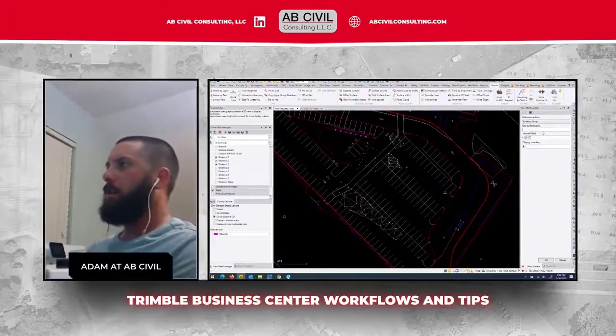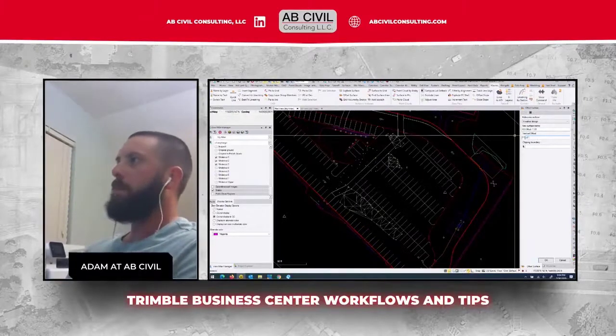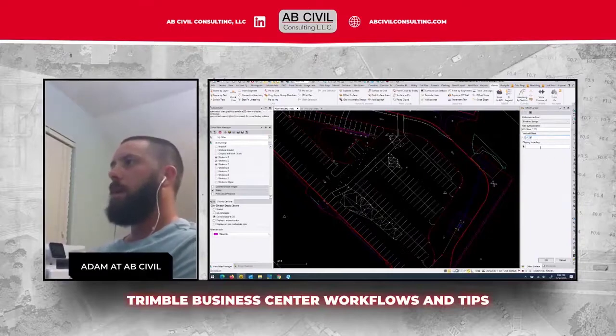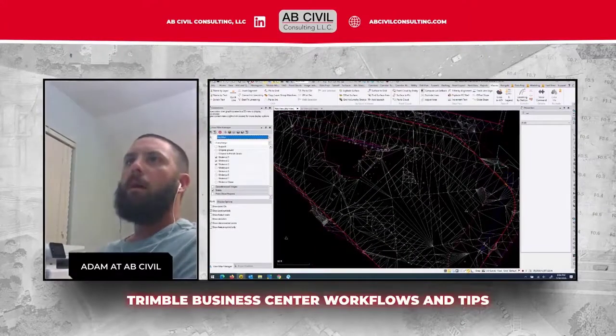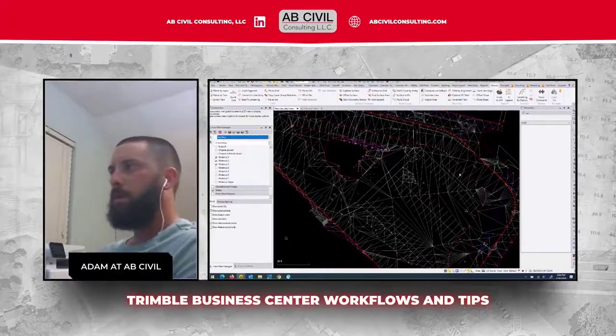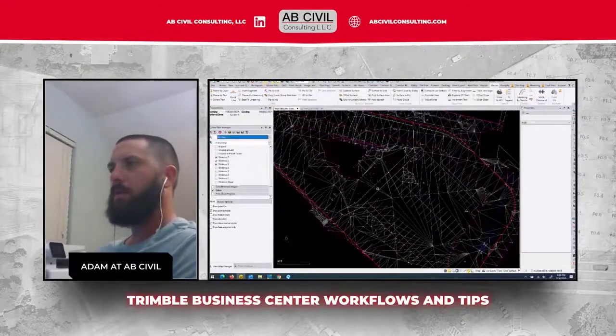So finished design, new surface, I'm going to do FD offset minus 1.33. Vertical offset minus 1.33. No clipping boundary. Just going to hit OK. All right, so there's a surface. I'll just change my sampling distance to 5 to tighten up the way it looks.